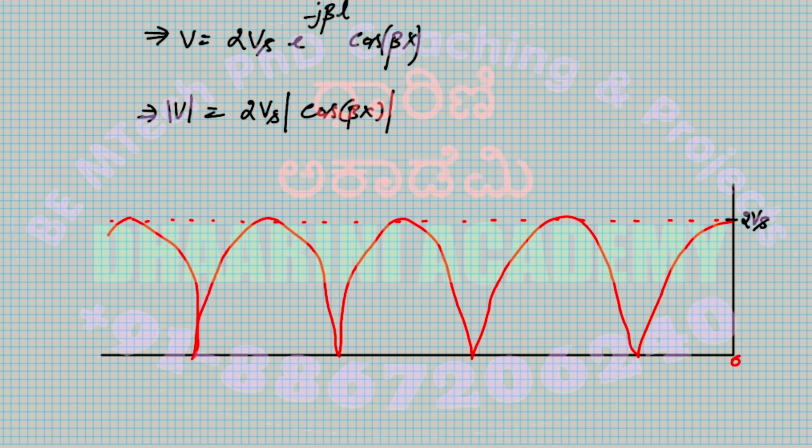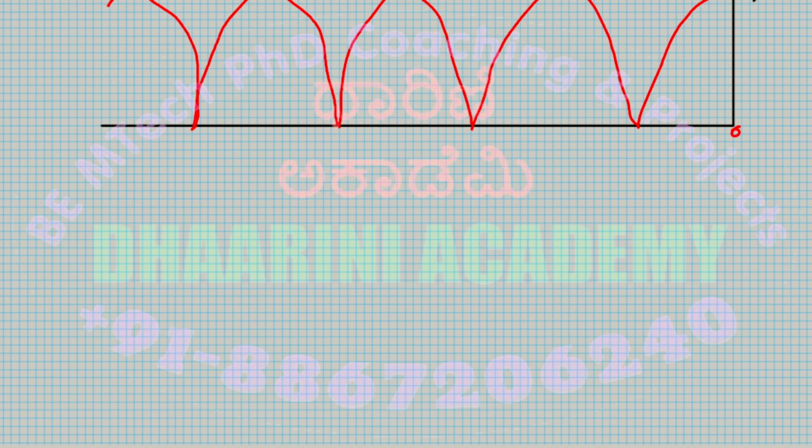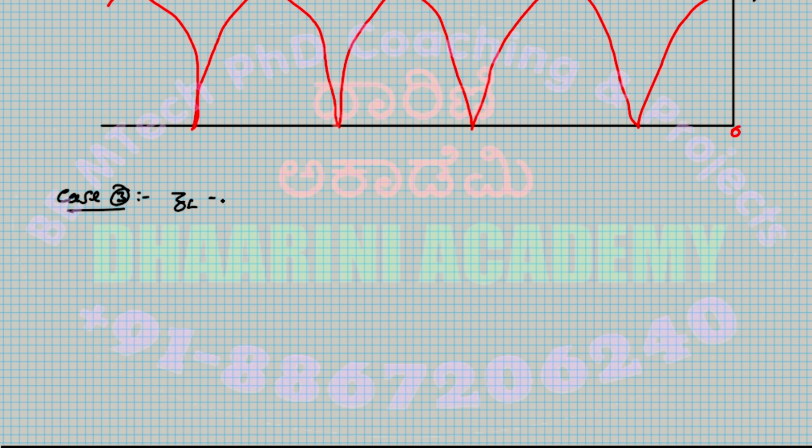Other than these two, the standard format is you have some other values of ZL. So this is case number 3. The ZL will be written as RL plus j times XL. So in this case, this is a complex load. What's the meaning of this? What will be the value of rho? Rho is also complex, correct? Do you remember? So now the rho is complex.